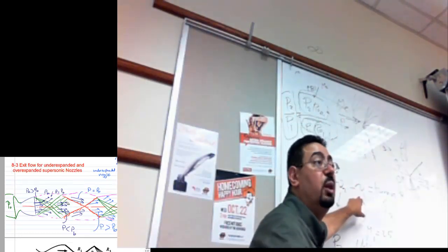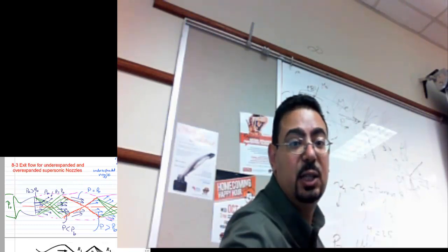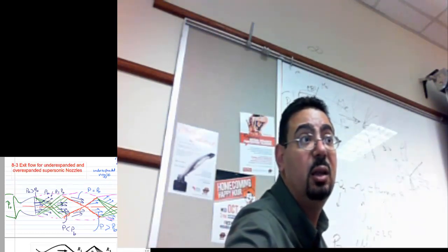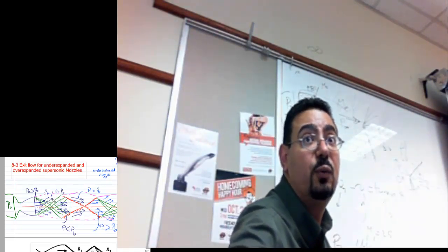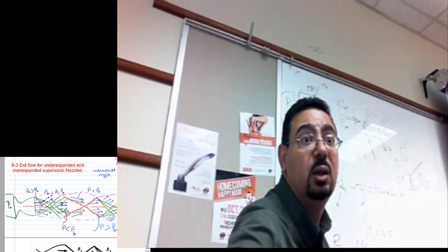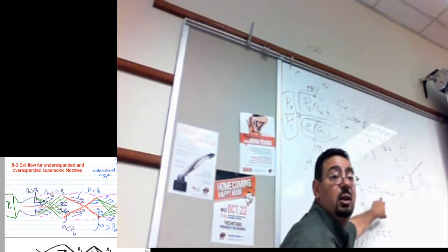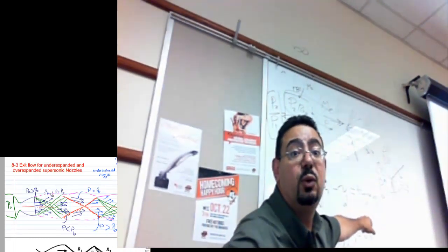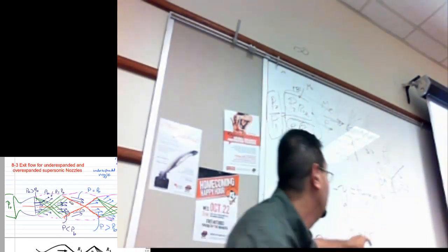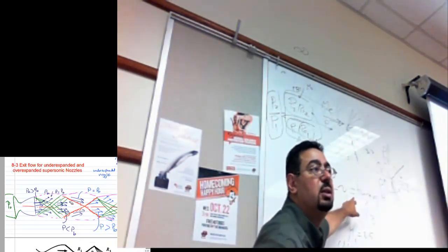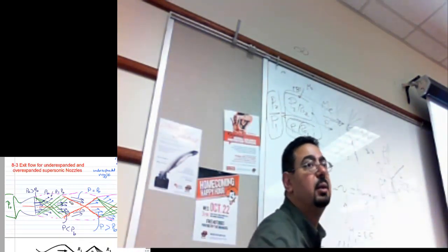That's why, because you're solving for that pressure. That's the unknown. We know the Mach number before the second expansion fan. We know the Mach number here, right? We just solved for it when we solved the first one. So we know that Mach number. So obviously we need the turning. We need to know the turning so that we can solve for the Mach number after the expansion fan. So that is the question. What is the turning? Excellent.